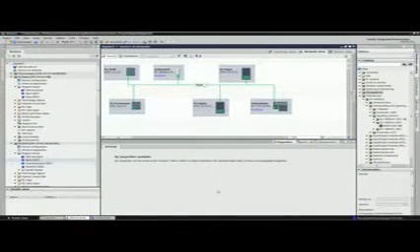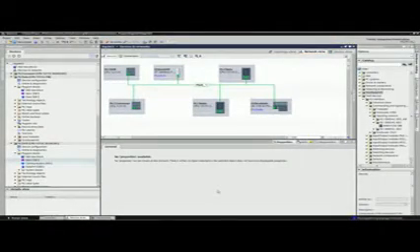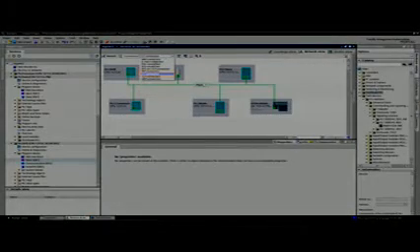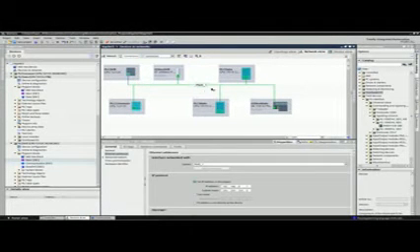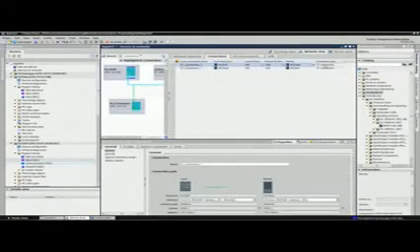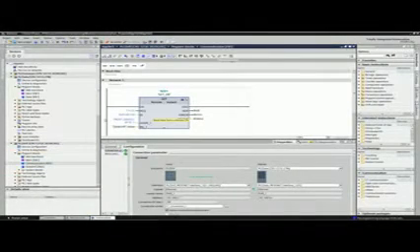To create a connection between two CPUs, begin in the Network view. Now click on Connections. To create an S7 connection, select the appropriate menu item. You can easily create the actual connection with a drag of the mouse. To confirm that your connection has been created correctly, you can check the Connections area of the table. Now you can exchange data over the corresponding blocks of the user program with a partner CPU.